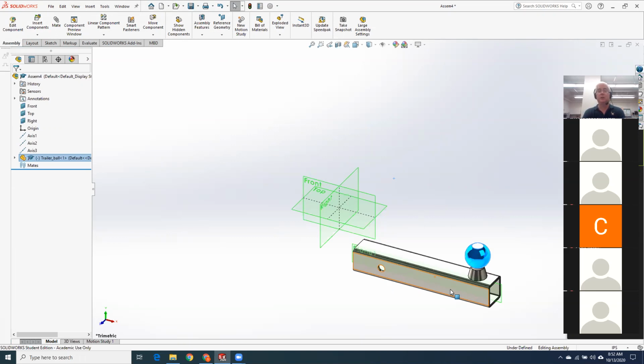So technically, no. And there are some times where you just may have to do it. So if you've got some ergonomic coffee maker and there are just no uniform faces on it, yeah, you might have to mate it planes to planes. But I would say try to do it the simplest possible way and match the mechanical assembly first. Then if you got to get exotic, then get exotic.